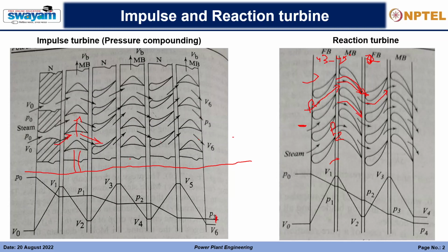So this will have a whirl component, VW. This whirl component is responsible for the blade movement, since it is giving a thrust to the blade. So the whirl component is perpendicular to the axis direction, right? More like normal to the blade, if you can see. See, the blade is like this.